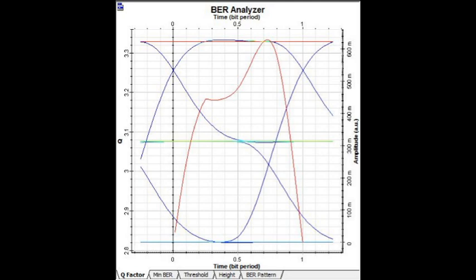When the attenuation is varied up to 500 dB per kilometer, the good Q factor output can be obtained in range of 3 meter, where the maximum Q factor value is 240.169 compared to the other range, which has a lower value. This is because theoretically, the higher the Q factor value, the better suited for the optical wireless communication system.